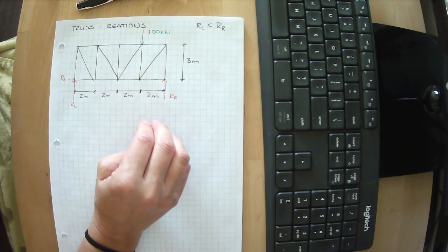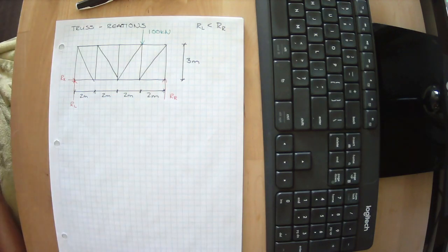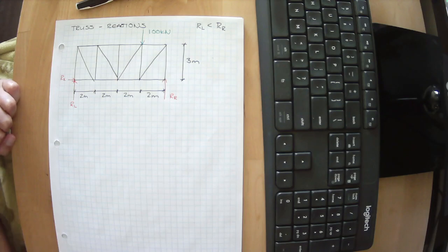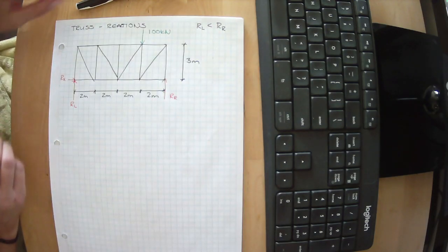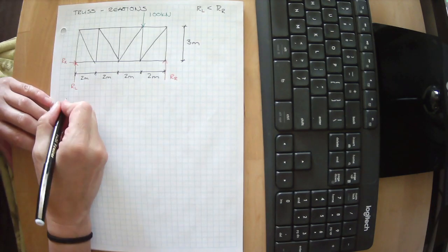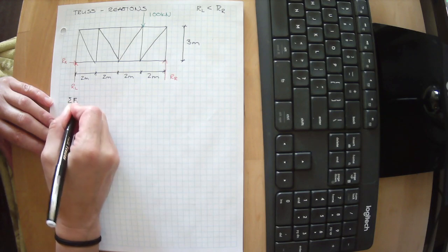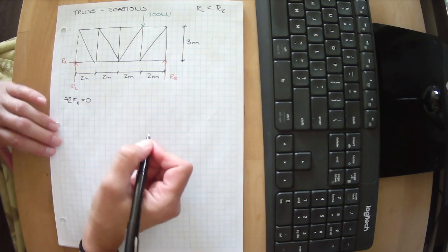If I sat further over on a table, more of my load would go to the reaction, or the legs of the table, that I'm sitting closer to. And so this is a nice check to figure out if what we've done mathematically is correct. So let's start by summing the forces in the x direction, where everything in that direction is positive.